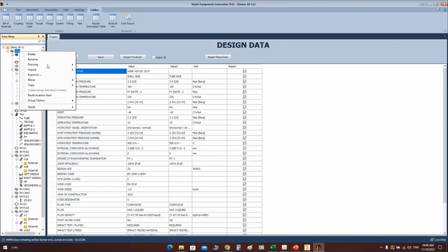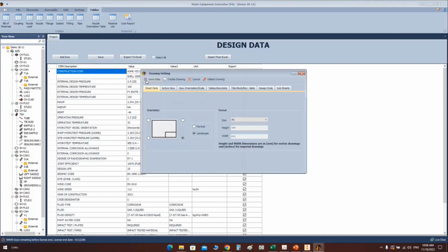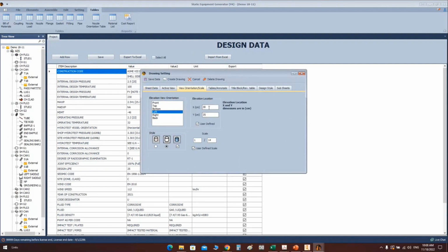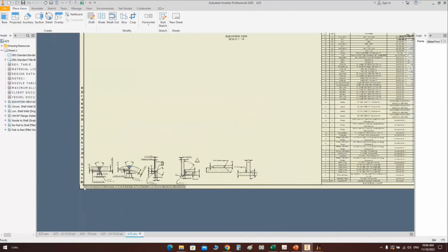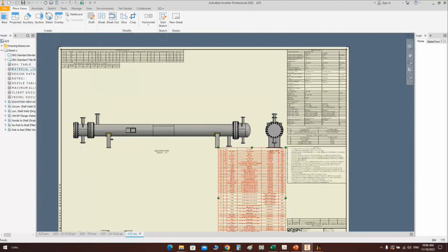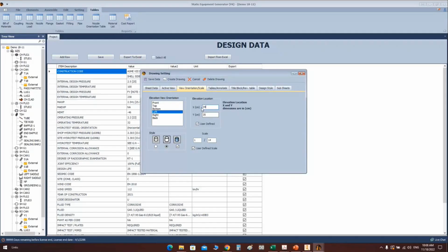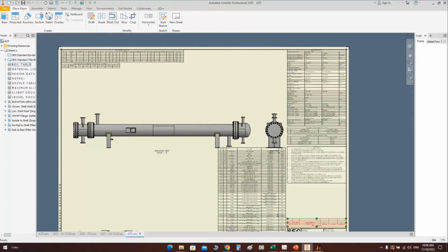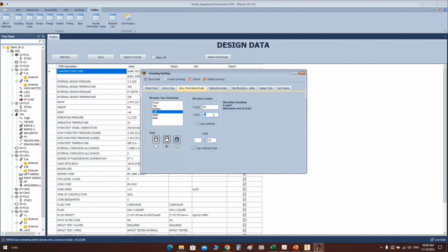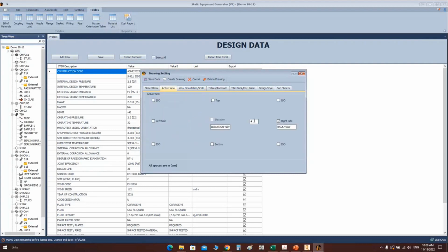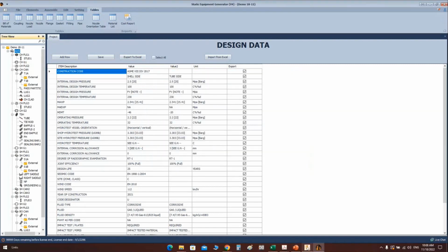So if we come back here and from drawings view, we will change the location in the X direction. The X direction, which is the location from the data point here. So it will be, let's say, 34 centimeters from bottom, and keep the Y location as it is, or we can move it a little bit. Let's make it 33 and decrease the spacing between the two views. And let's click on create.